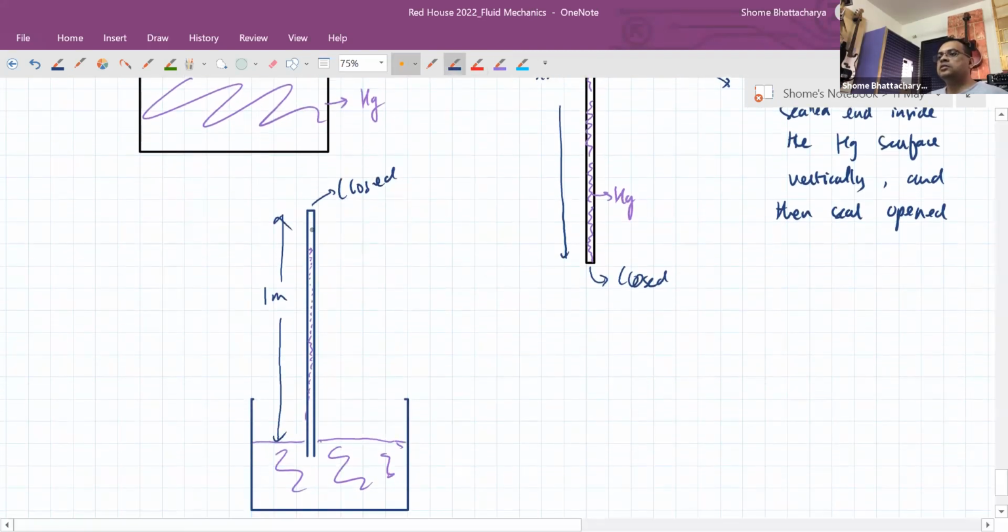So this is a vacuum gap, and the level of mercury that remains inside, we can measure to be X. Okay. So the moment we measure that value X, if we compare the pressure at these three different points, A, B, and C, we can see that the pressure at the point A will be 0 because there is a vacuum gap above it.